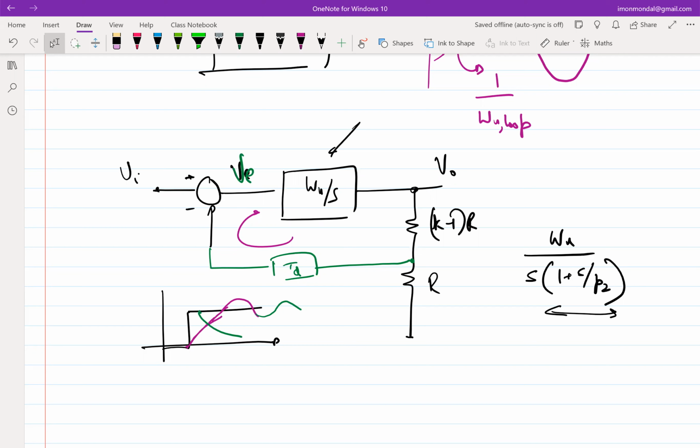Sir, yes. This type of pole can give an ideal delay within some frequency range, right? As long as you can satisfy omega much less than the pole, the tan inverse can be expressed as that argument. Then it becomes an ideal delay. So for a delay of T_D, it will be e to the power minus s T_D in the Laplace domain.